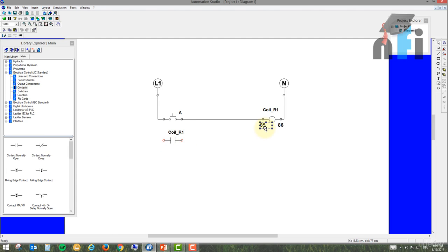So common was pin number 30. So I will just write here. The common I'm connecting directly to my line voltage. And this voltage is either 220 volts or 110 volts, depending upon which country you belong to, because somewhere we have single phase 110 volts and sometimes single phase is 220 volts. It depends on the location where you live. All right, in my country we follow 220 volts, so I consider L1 as 220 volts.